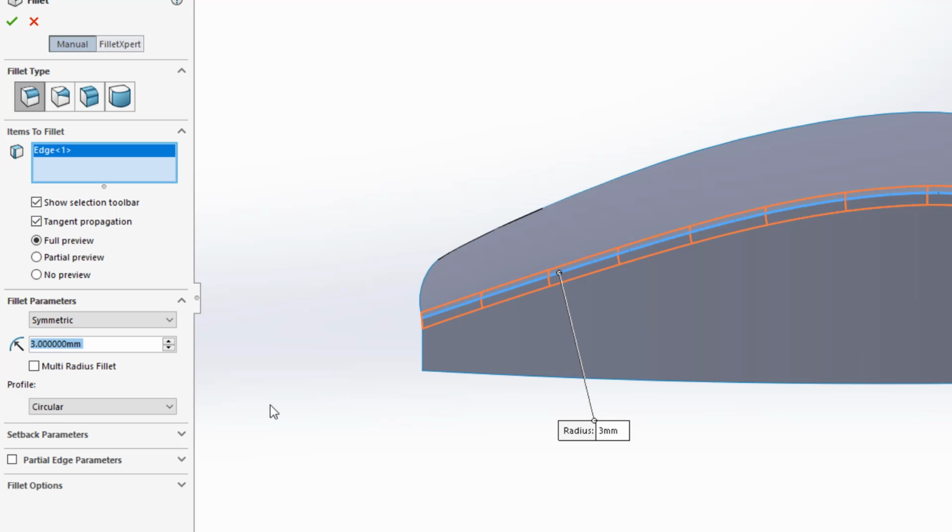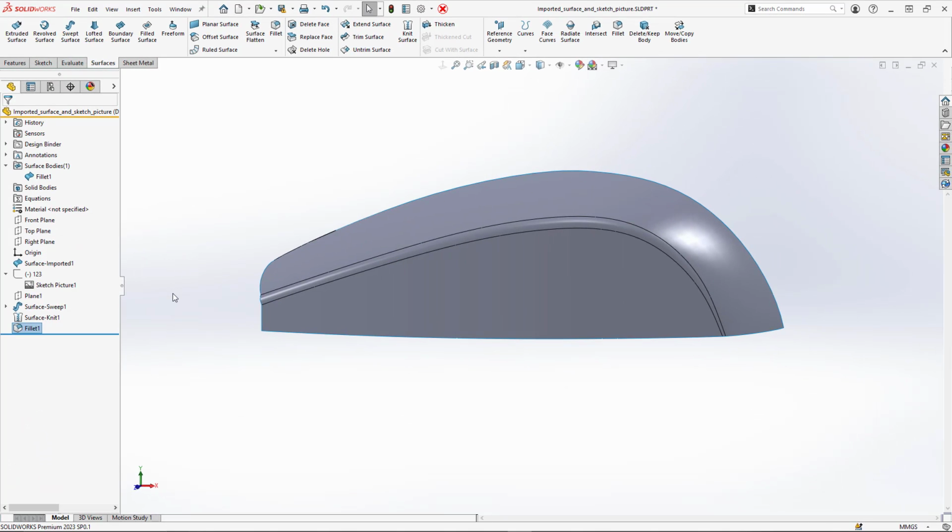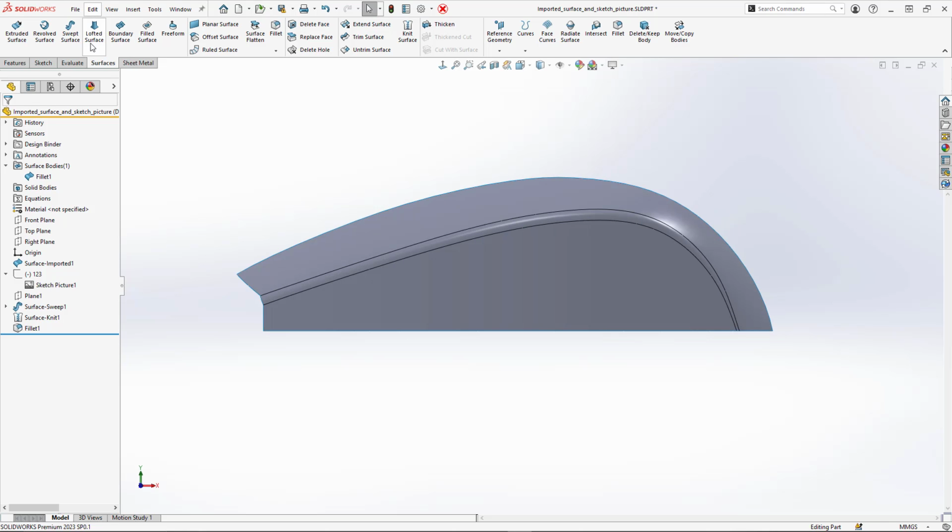From here, under the profile of the fillet parameters, this is where you are actually going to see the specific setting for curvature continuous. Again, if you didn't realize that this was there, this is one of those questions that you could end up wasting a significant amount of time on when the fillet already does this for you. So this is one question where there is an anticipation that it's going to go by very, very quickly.